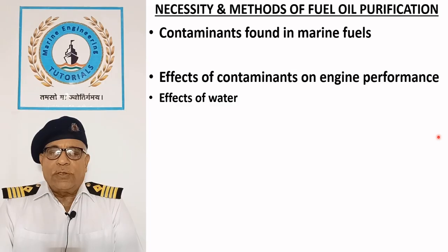It starts microbial growth at the fuel water interface and forms sludge. It leads to poor combustion, resulting in black smoke and carbon deposits. It can also form emulsion, which is difficult to separate.